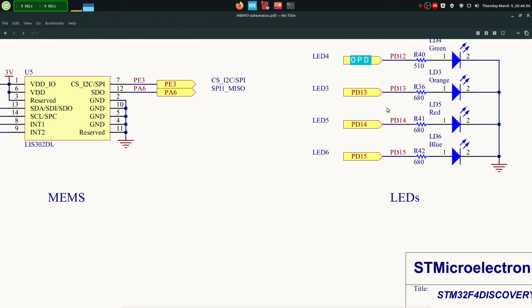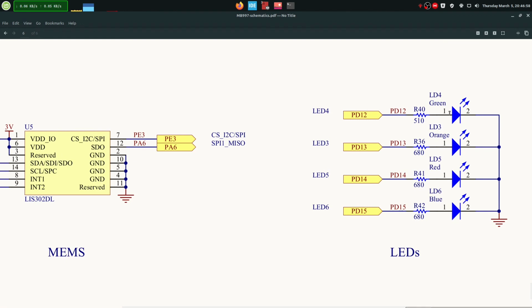Okay, so this pin, we said, has to be high in order to turn the LED on. Great, so we know that these LEDs are controlled as active high. So to turn them on, or emitting light, you have to put the control on high. Great, so now we know what we need to do.